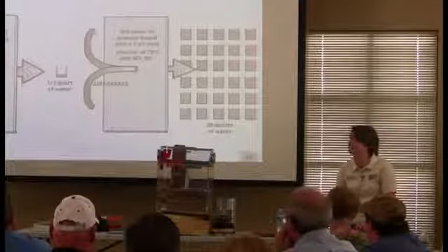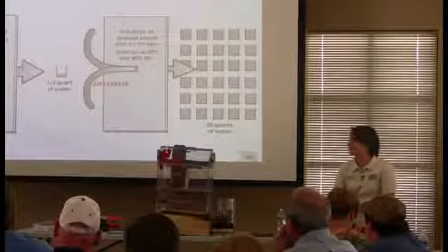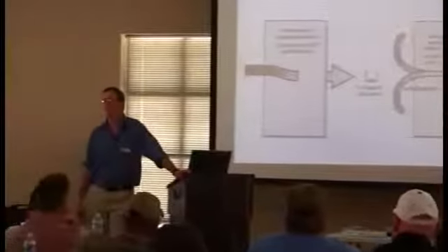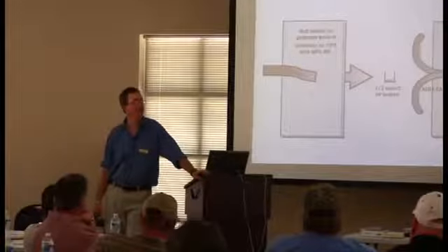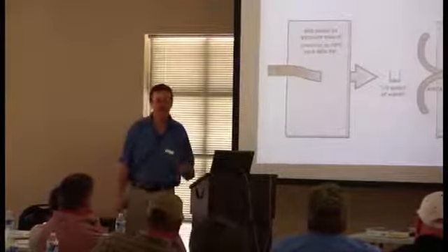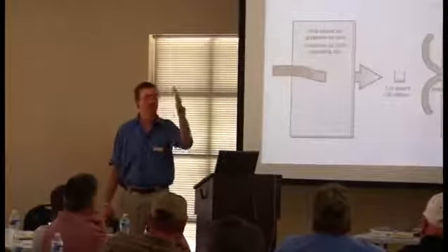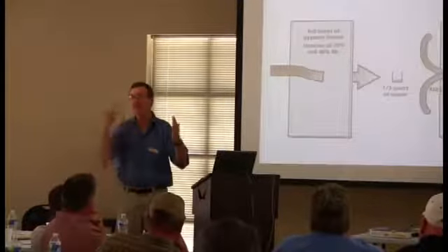Yeah. So we don't want to, and we learned a lot of lessons about this. Anybody remember the old synthetic stucco on houses? We put synthetic stucco, which is a cladding that actually can work really well, but we put it up without a drainage plane behind it. That was the big mistake.